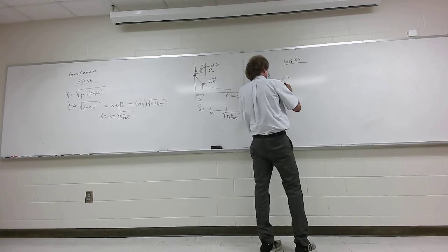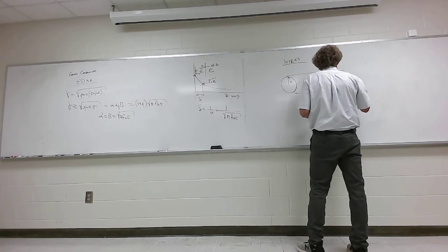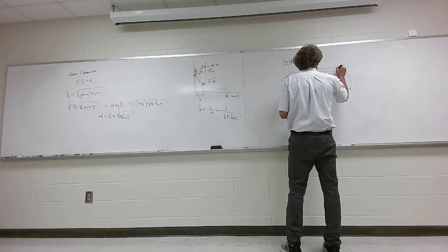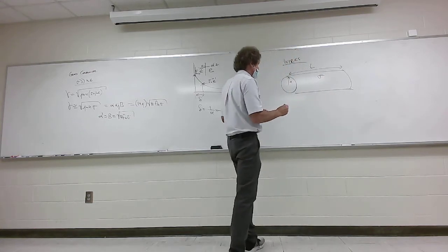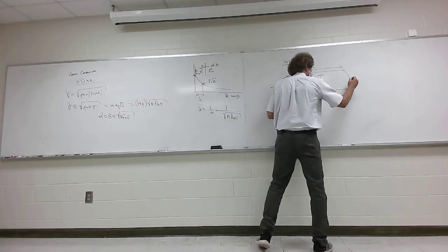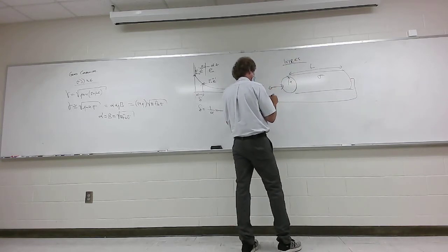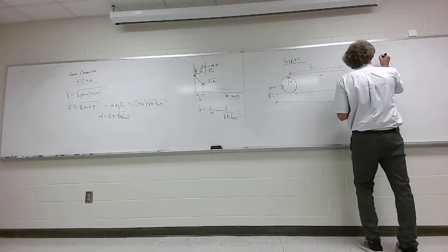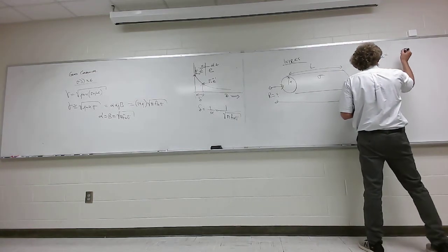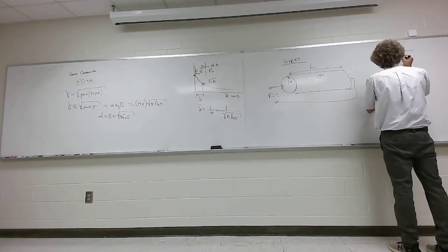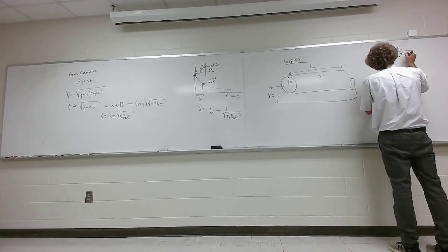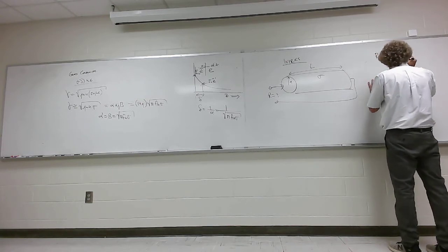When you have a wire, if you have a wire with a radius A, and it has a length L, has a conductivity sigma, then the resistance between this end and this end, if we talk about the DC resistance of that wire, it would be proportional to the length, inversely proportional to the cross-sectional area, or pi a squared, and inversely proportional to sigma.